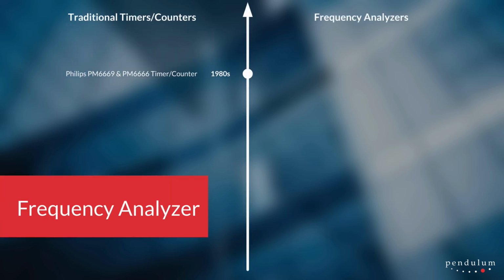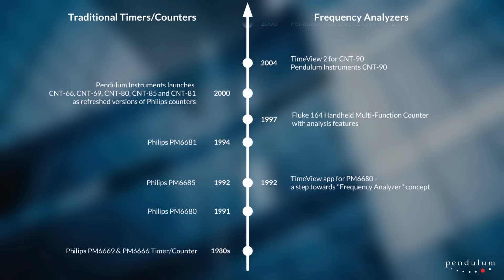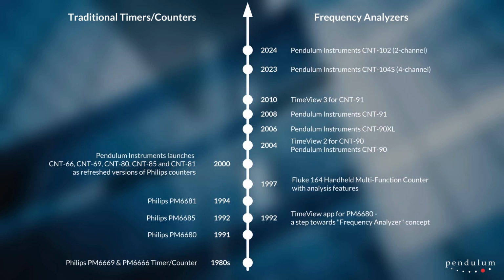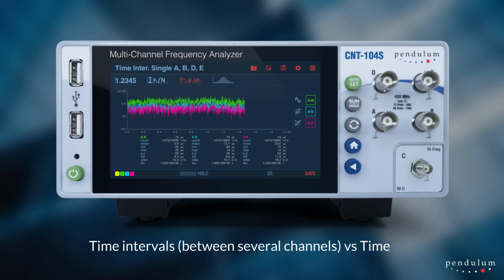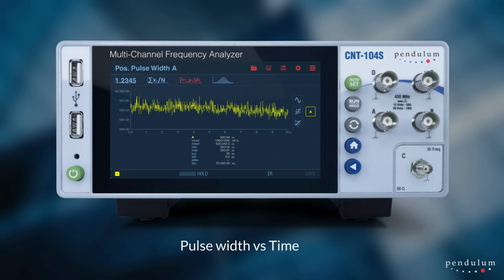A frequency analyzer is an instrument that represents the next step in the evolution of traditional frequency counters and high-resolution time interval analyzers. Such instruments do not record signal waveform, like oscilloscopes, nor do they show a signal's spectrum. Instead, they show how the selected measurement parameter, whether it is frequency, time interval, or some other, changes over time.